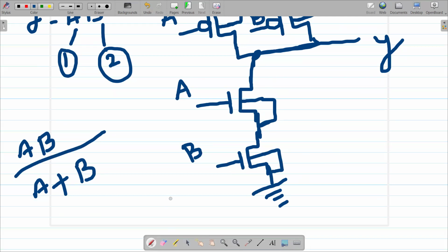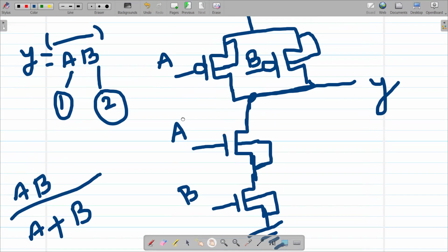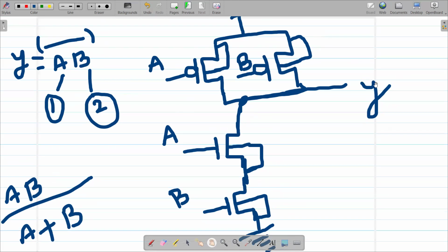So now what is been said earlier, by default, CMOS technology will give inverted output, right? So this output is in inverted form. So that is what NAND gate is. So you don't need to plug in the inverter at the output of this, after this Y. You don't need to connect this Y to an inverter and take the output of that inverter. So that is not required. If it is AND gate, then you have to develop one inverter here.